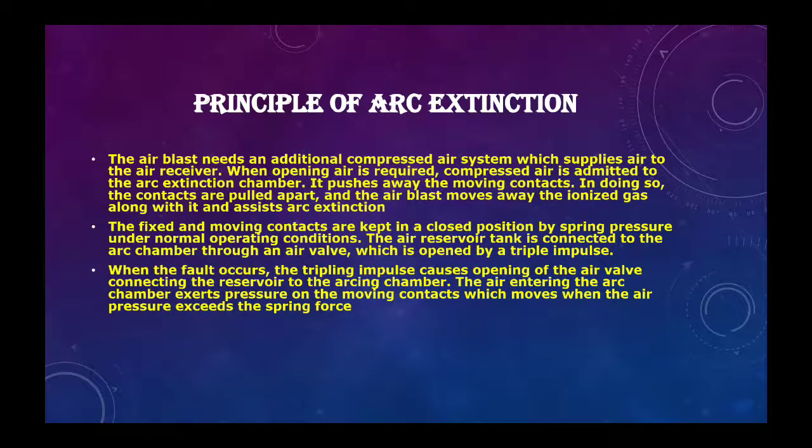When the fault occurs, the tripping impulse causes opening of the air valve connecting the reservoir to the arcing chamber. That means when the moving contact is opened from the fixed contact, then the tripping impulse causes opening of the air valve connecting the reservoir to the arcing chamber,